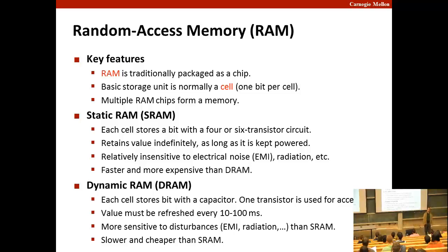But I would have to check. If you're interested, take recording. Okay. So your hypothesis is that it does what? It's supposed to go through every single horizontal row and then access the specific cell, and then compares it to some threshold voltage, and then if it's above the threshold, then it declares that to 1. So then when it gets the instruction to refresh it, then it puts back in the VDD. Otherwise, it just leaves it grounded.